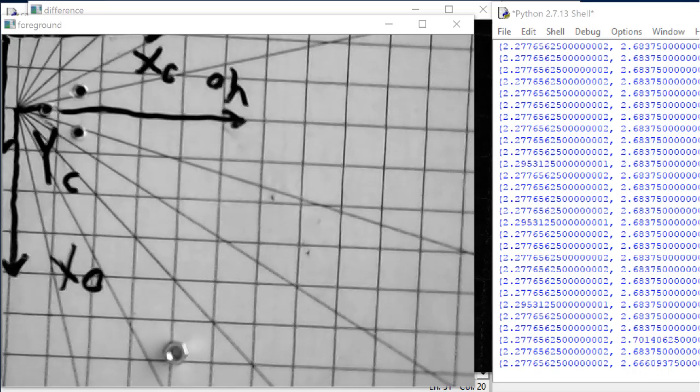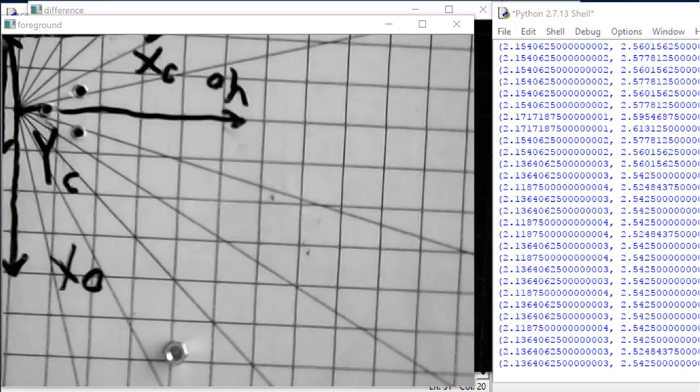Next, let's find the displacement vector. The displacement vector is the displacement from the center of frame 0 to the center of the camera frame. The center of the 0 frame is right here, and the center of the camera frame is right up here. So the vector that we want is this one. I want to write that vector in the 0 frame.